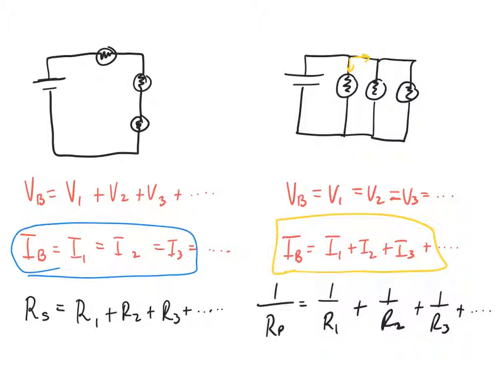Now, that's really the gist of it for circuits, but the key to remember is to do what for every circuit? When you're given a circuit with like 5 resistors, what's the first thing you have to do? Good. Find the total or equivalent resistance. If it's in series, then you just add. But if it's a combination of series and parallel, you have to look at that individually. So whatever's in series in that made-up circuit is the thing that you focus on first. So let's make up a circuit together real quick.